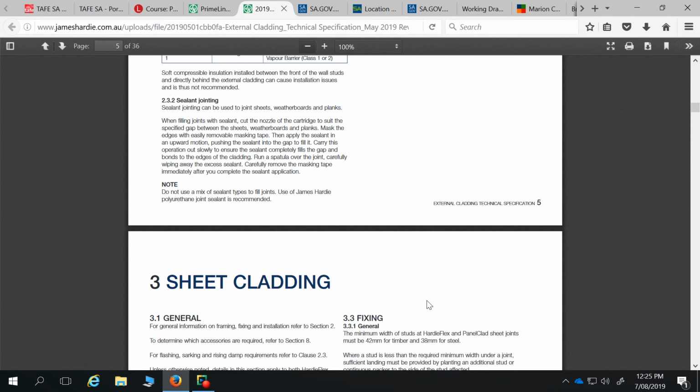So the reason there's two differences, the drafting pattern should be used for the 2D stuff that's not going to be 3D orientated. Floor plans, maybe just on elevations if it's something specific, but in the outside of the model, like your roof material, illustration, your cladding, choose a model pattern. Okay, it's not hard to change it if you get it wrong, but just remember. So that sort of gives you a bit of a head start if you want to start drawing today.